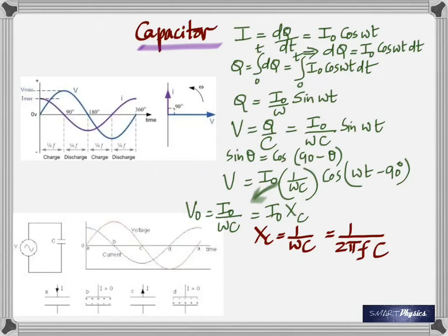That's why it's called a bypass capacitor. It bypasses the AC and blocks the DC. There, you got it. Then you listen to music. If it blocks both, then you don't hear anything. That's just one of the functions that I gave you. A capacitor, an inductor, and a resistance are so useful. Look at this graph now. Before we let this go and I give you a break, look at this. Which one is leading? You don't know.